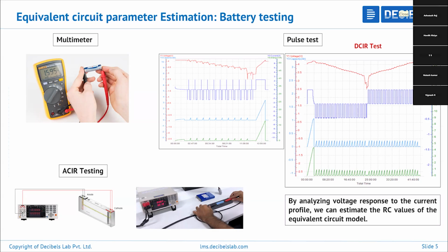AC excitation at a high frequency of 1 kilohertz will show you the internal resistance associated with the battery. You can see in the figure where the person has connected this battery, and in red it shows the OCV around 3.264, and the resistance associated with it is about 3.61. Sorry, 3.264 is your OCV, and 3.61 is associated with your resistance.